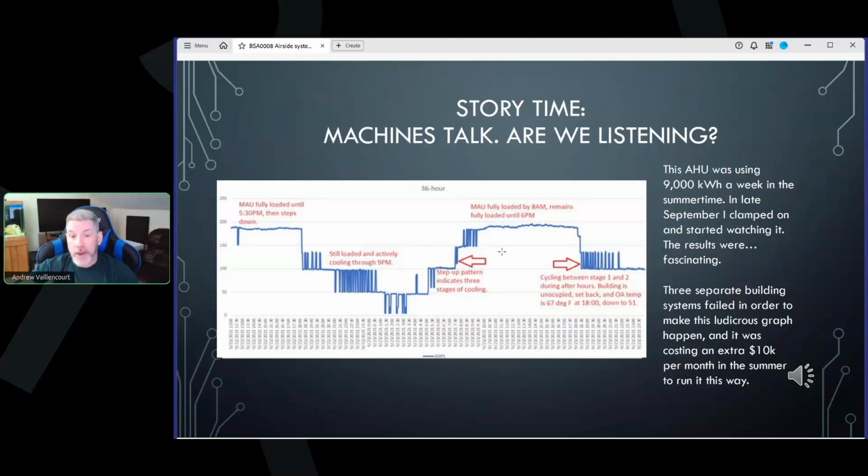Outside air is expensive air. It takes a lot of energy to condition it. There's a correct amount to use, and ASHRAE tells us what that is. It's not one of those situations where if a little is good, more is better. There's no actual improvement in air quality going from the ASHRAE standard for whatever it is you're doing to twice that. The human nose, the human lungs will not tell the difference.